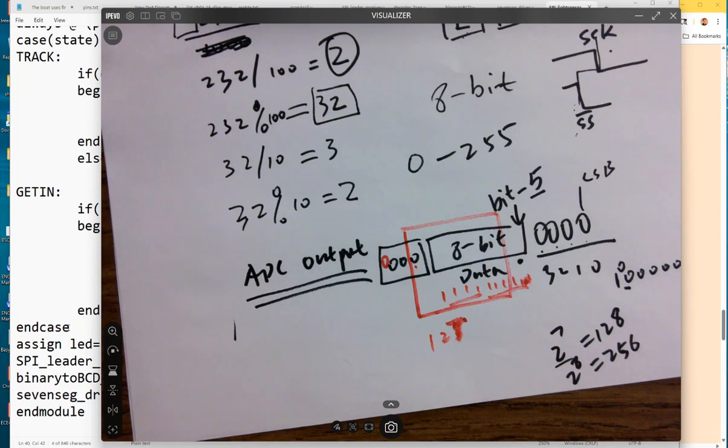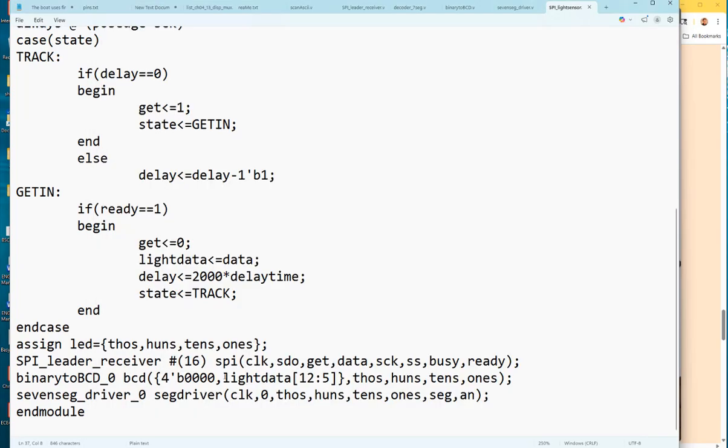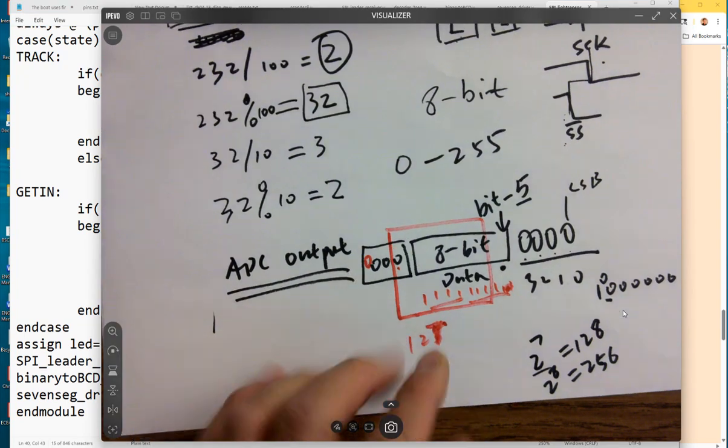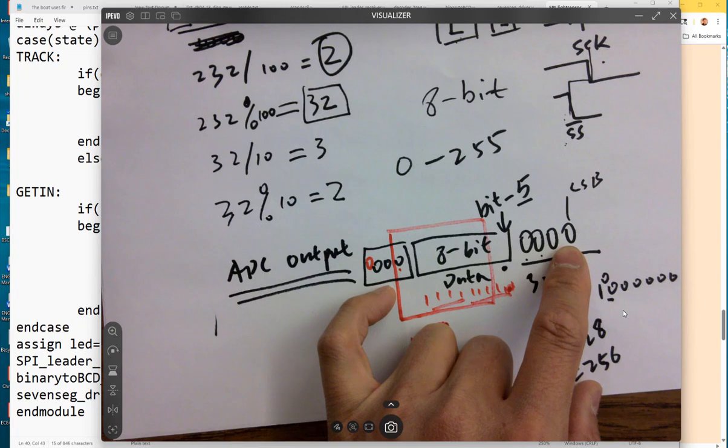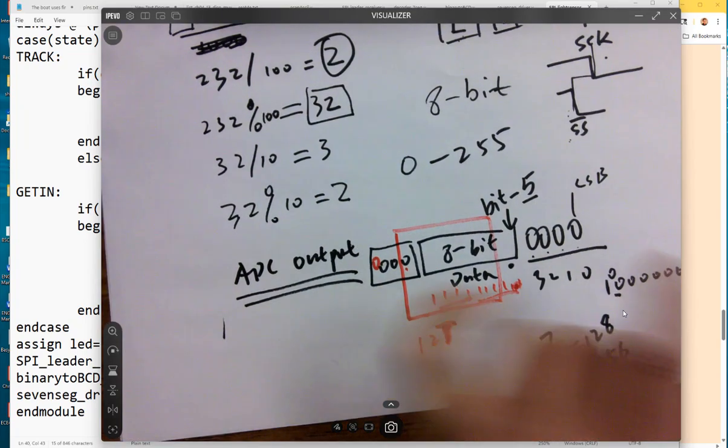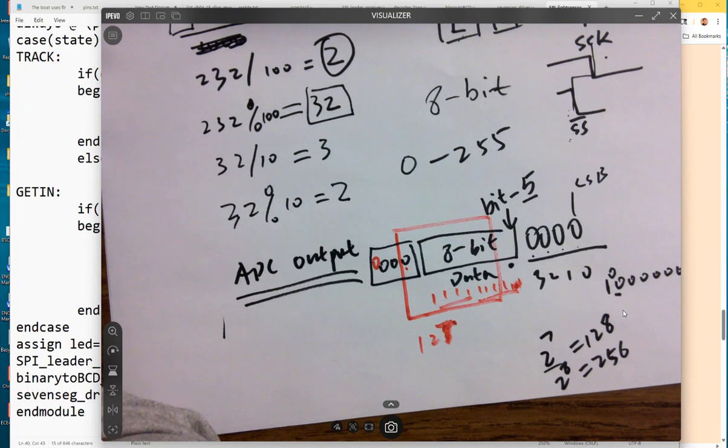Okay, but this one does give you good results, unless the data sheet of the ADC is inaccurate. But anyway, we know some of the tricks over here. It's just the ADC outputting a certain pattern of data like this. So one way to look at it is we can throw the entire 16 bits to all 16 channels of the oscilloscope. It has a digital data input. You can just look at all the bits, right? So that's another way to monitor it.